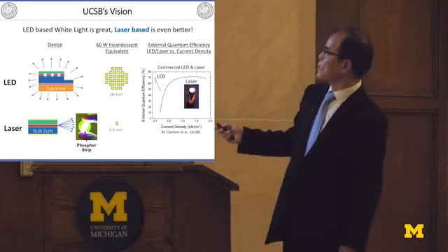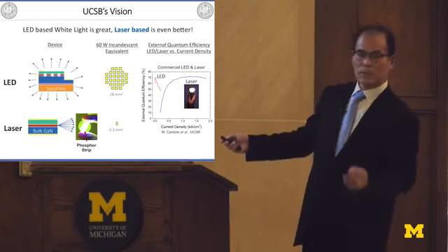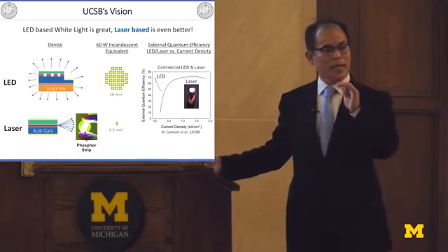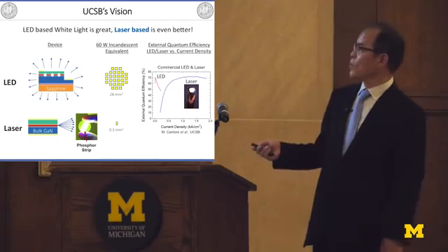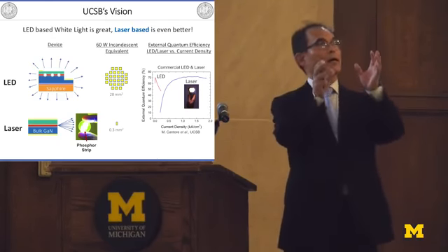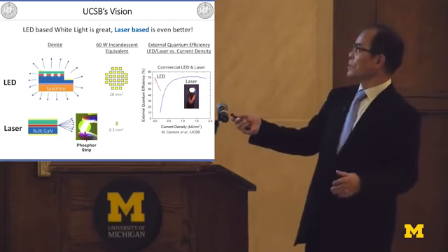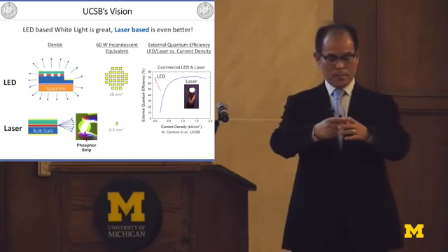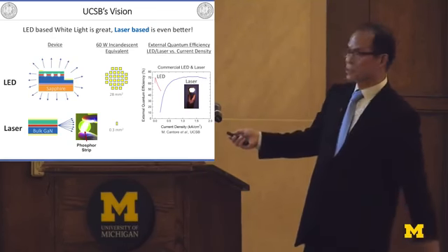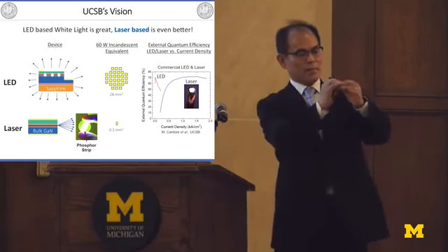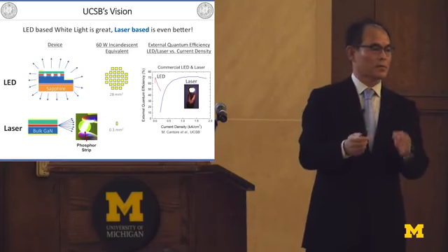So in order to reduce the current density, emitting area should be very large. But in the case of laser diode, current density is 1,000 times higher than the LED, so we can use a very tiny chip. This is the future technology, because when we make a lamp, in the case of LED, we need this size of emitting area, means the lamp becomes huge. But in this case, a tiny chip, lamp is this size. So systems become very, very small.